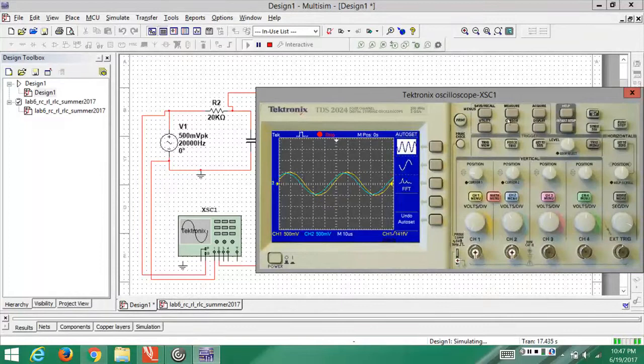I can say this just by looking at it, without measuring using any cursor or anything. But to be certain, I will use this cursor button over here to bring in two cursors on the screen and then set them, one at the beginning of the waveform and one at the end of the cycle, so that I can mark the exact time where the cycle started and ended. That way I'll know if it spans 50 microseconds.